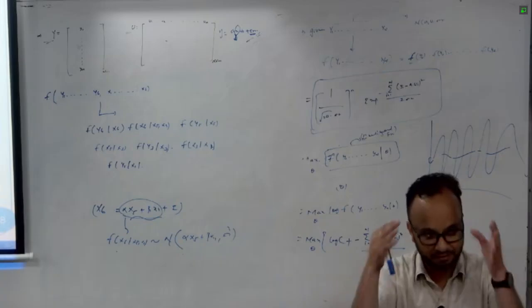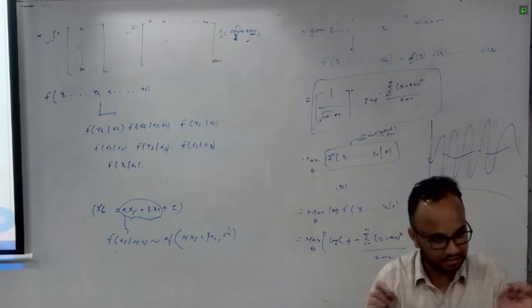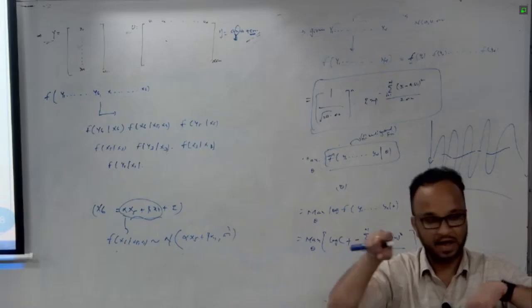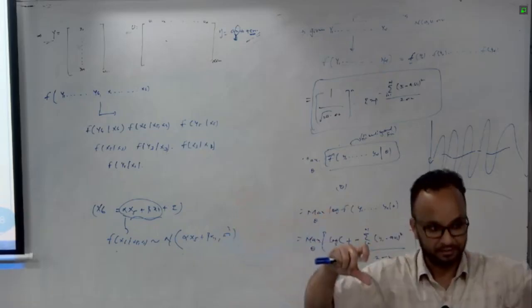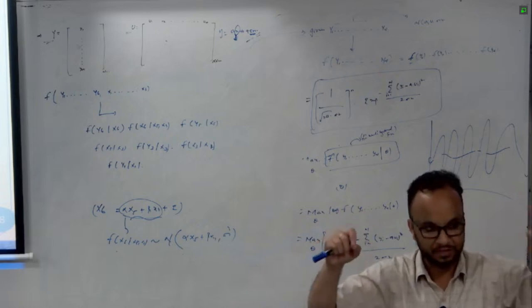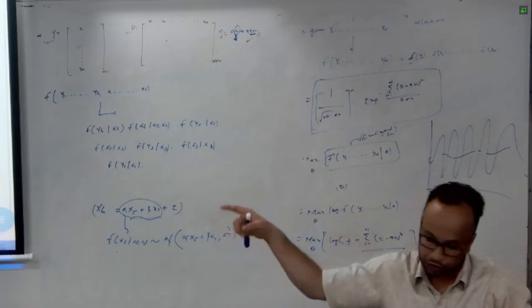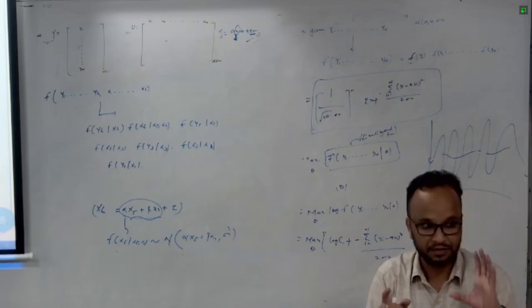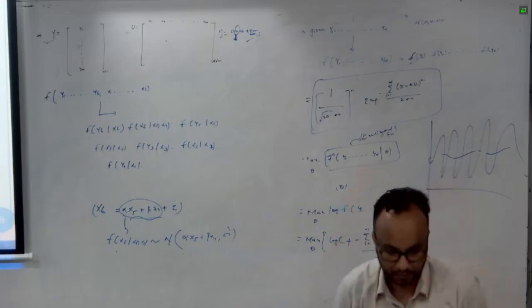In that case, one way is to do downsampling: only select the measured data. Don't select the NaN data; remove that entire row. If you have 10 variables and there are NaNs for a longer time, just remove the entire data sets. That is called downsampling. We sample only when the measured output variables are good. The other way is to use the EM algorithm and estimate those hidden variables. I don't want to delete the data because data is crucial and has good information. I want to estimate it without deleting the data points.